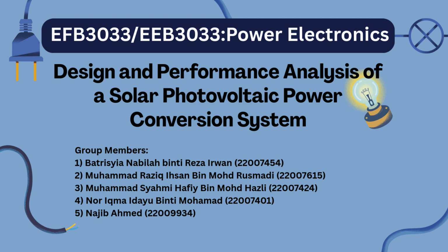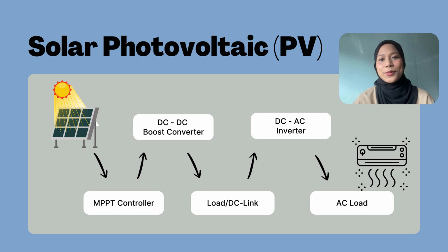Hello everyone, today we will be presenting our overall project where we design and analyze the performance of a complete solar photovoltaic power conversion system and simulated it using MATLAB Simulator. In this project, we designed the PV panel configuration, the DC-DC boost converter with MPPT control, and the single-phase DC-AC inverter. All these components were then integrated and tested through simulation to verify their performance.